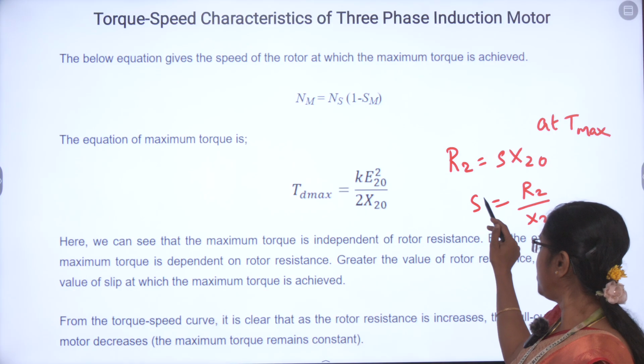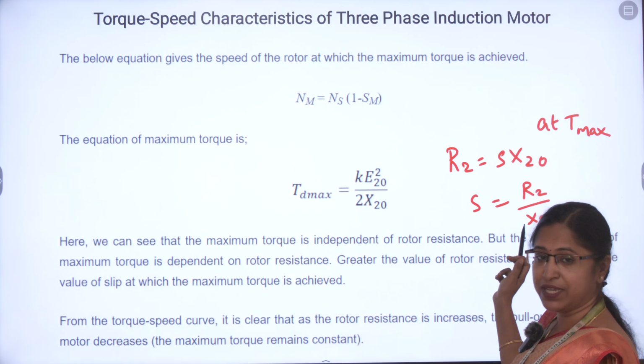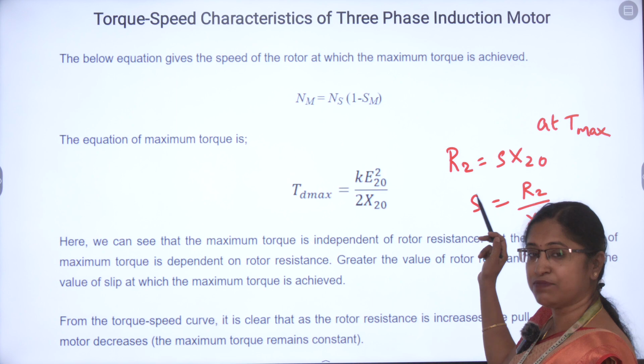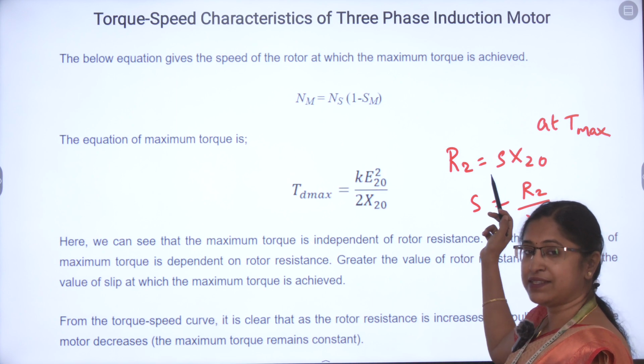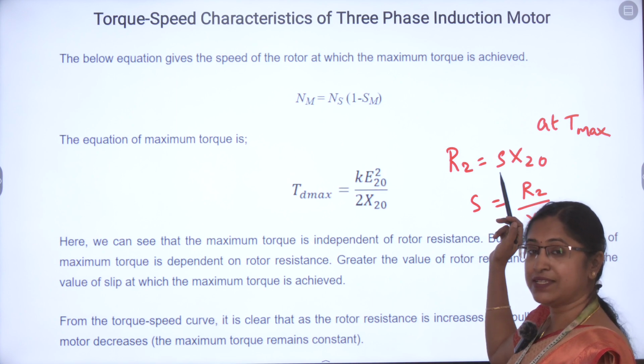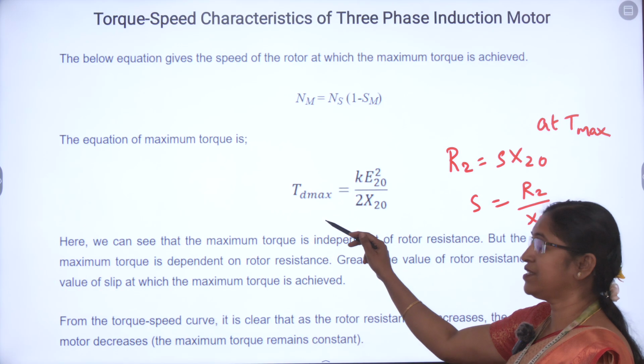So your S depends upon your resistance as well as your reactance. So when there is some change in your slip, the resistance value will also change. So resistance has a great effect in changing the torque.